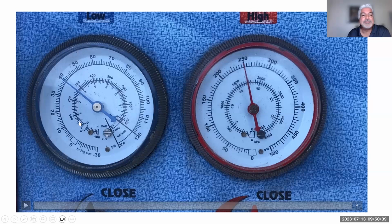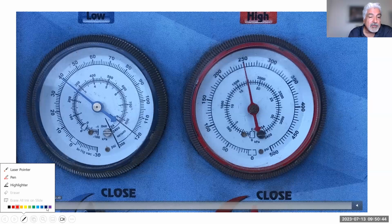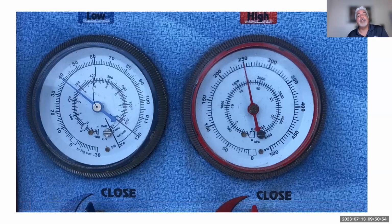So let's say, let me color code this guy here. Let's say I go ahead and turn on the compressor. I'm at 250 on the high side, but the low side is at 60, right? So I know that it's not in the 30 to 40 range, like the pressure temperature charts were showing us in part one.